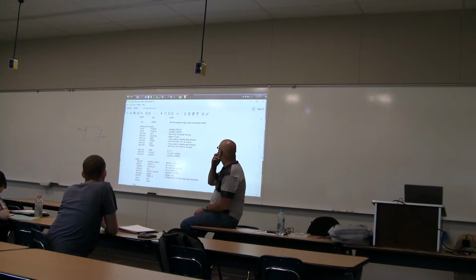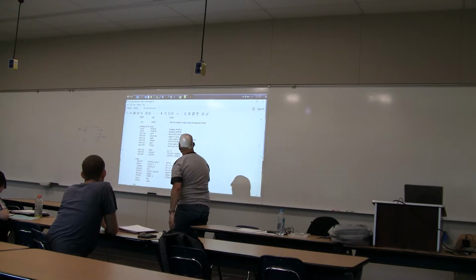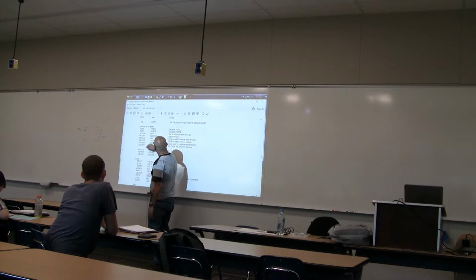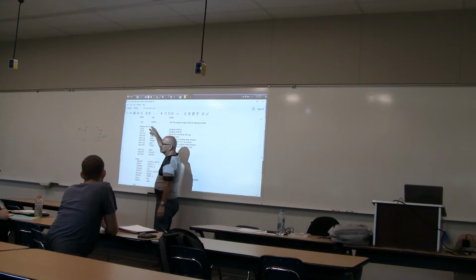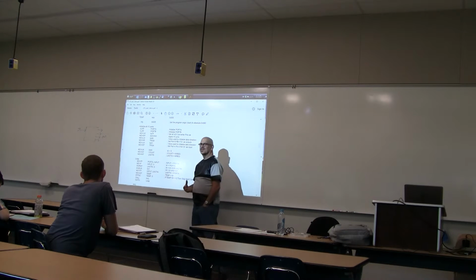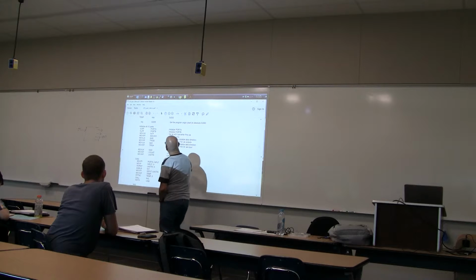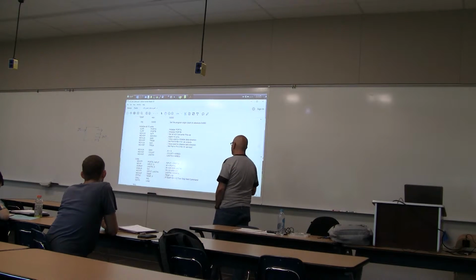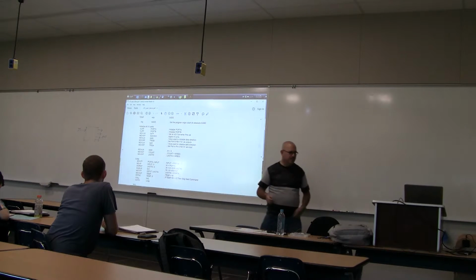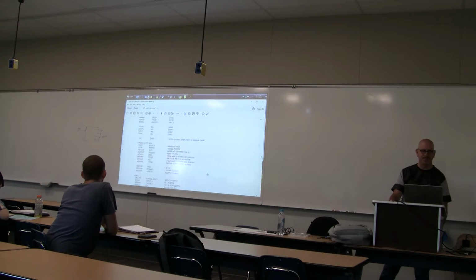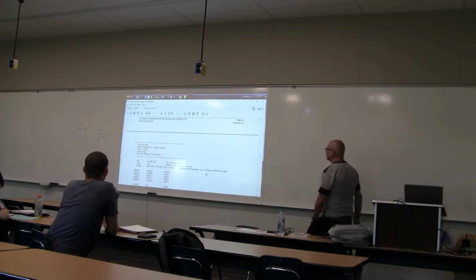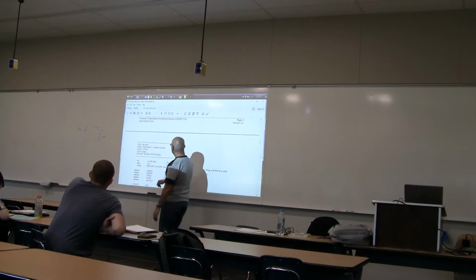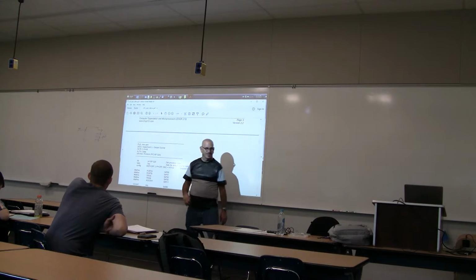So throw a comment in each line. Throw comments in the beginning of sections of code. All of this is doing what we call initializing the I/O ports. Just throw a comment up there and then put a space in there. And now if something's wrong with your initialization, you can look at this and say, oh, it must be something up here. And now you start going through everything that you did. And you can put comments in the beginning to describe what this program is, who wrote it, the date, and so on and so forth.